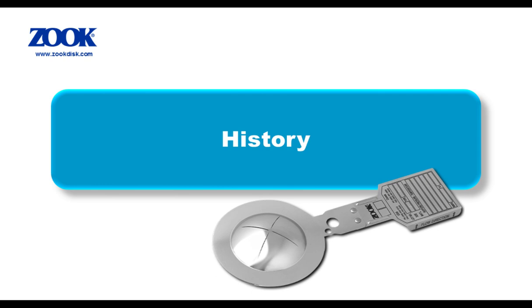It built on the simplicity of the original disk design, adding 2 features to improve functionality. A reusable holder was introduced, improving burst repeatability by holding the metal foil consistently and providing a better, more reliable seal between both the disk and the holder and flanges. It also included factory pre-bulging of the disk foil to improve cycle resistance and reduce fatigue. The design is simple and fail-safe, relying on the tensile properties of the foil to control the bursting pressure.